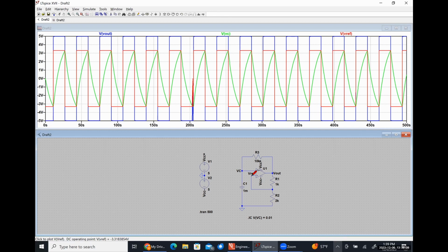Ground, and then usually, so this is a differential pair where you apply a positive input here and a negative one here. So this would be your non-inverting input terminal, this would be your inverting input terminal, for an op-amp specifically. That's perfectly matched, so these would both be NPNs or PNPs. This is just a differential pair that's being biased by a BJT current source.